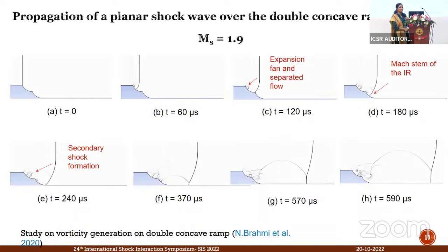and it has a lot of changes. So the flow here itself will be a combination of both subsonic and supersonic, and the Mach numbers change according to the shock speed. So when you say supersonic, are you talking about the lab frame or the shock Galilean transformed frame? In the transformed frame. So that is how we will be plotting the shock polars. If it is supersonic in the transformed frame, that does not matter, because your expansion fans will depend on the flow Mach number in the lab frame. So it should not matter if you have a supersonic flow in the transformed frame.